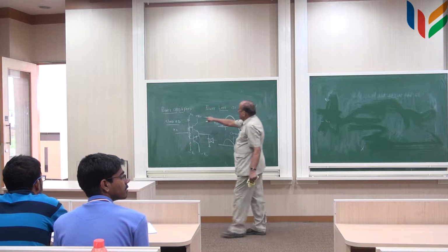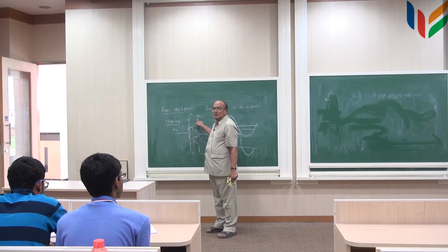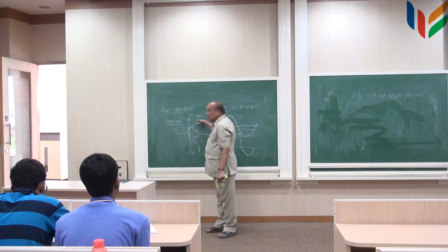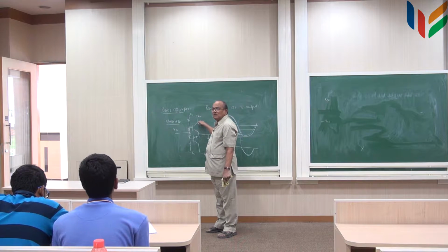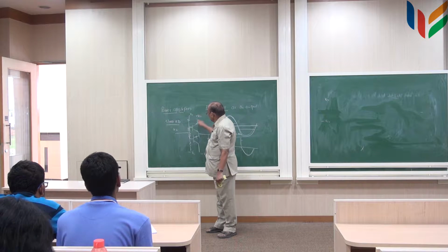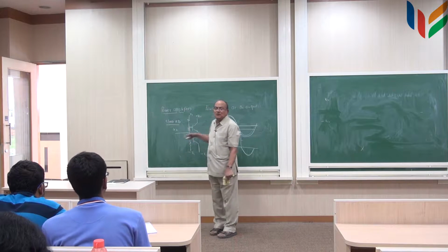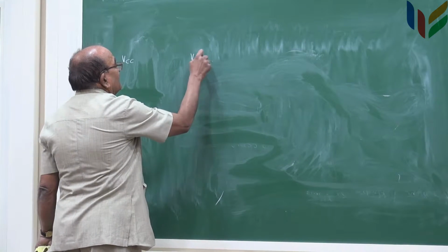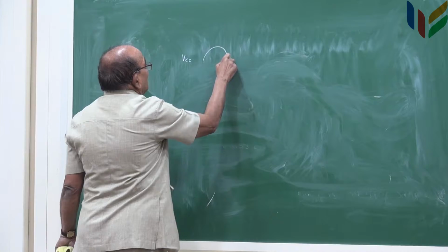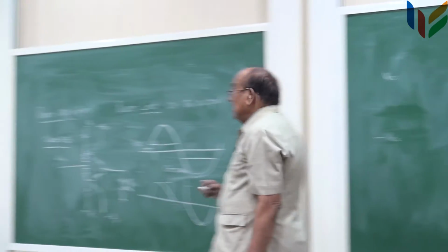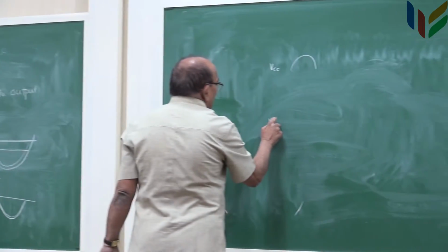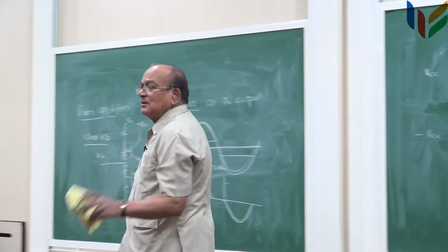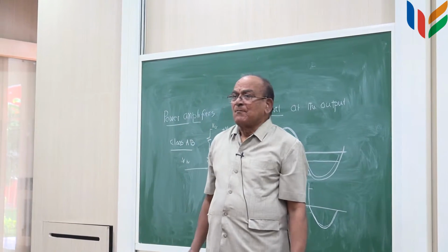This power supply is a constant voltage power supply. So, the voltage is VCC all the time, and current through this is only for half cycle, corresponding to when this is conducting. So, the voltage is constant and current is a half sine wave. In this one, voltage is minus VCC and current is another half sine wave, which is the remaining other half.